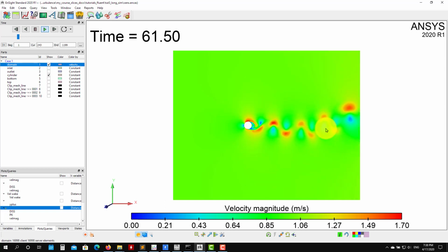So see that at 50-60 seconds this wake is oscillating. I will let it run, and it will oscillate up to 300, but there will be a point after which it will get more stable. Okay, so it keeps oscillating, see that it's getting better here, but still you see that switching. Something that you won't see if you run the K omega SST or any of the viscosity models, or the standard ones, is this switching.